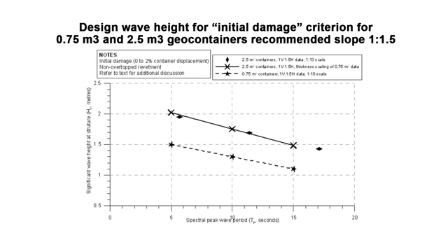So how this graph works, this is the significant wave height at the structure. So this is effectively the waves that are reaching the structure and potentially breaking on the structure. The graph goes from 0.5 metre up to 2 metres. The axis along the bottom is the wave period. If you're into coastal engineering, the Tp value, but if you're not, wave period is basically the time in seconds between the individual waves. So higher energy ocean swell has a longer wave period.